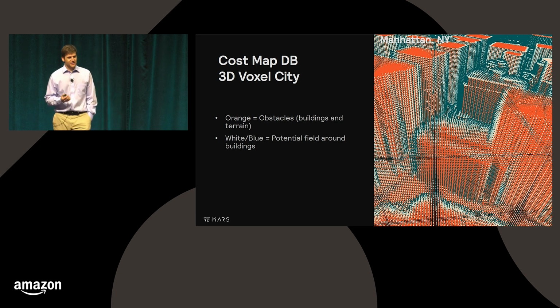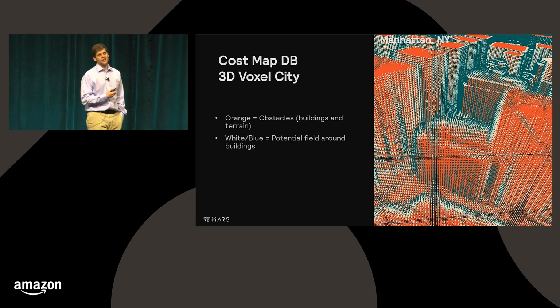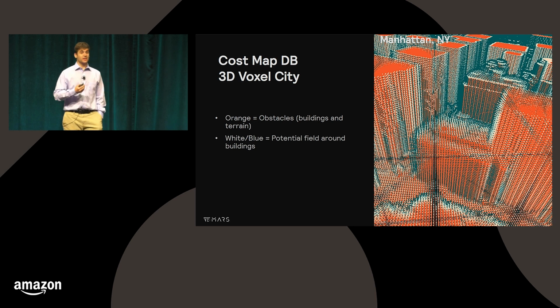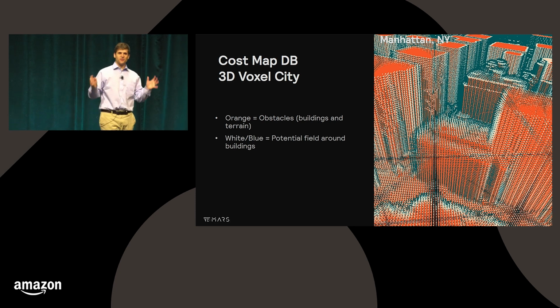For our cost map database, something we can do for basic path planning, to understand how difficult it would be to reach a landing site, is create basically a 3D voxel map that also has riskiness inside of it. What you're seeing here, the orange represents obstacles. This is Manhattan, New York, by the way. Those could be buildings, terrain and so forth. And this white and blue are potential fields around buildings, which help inform the planner to stay away from them.